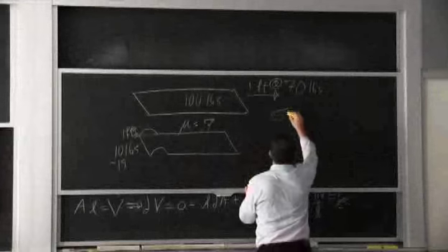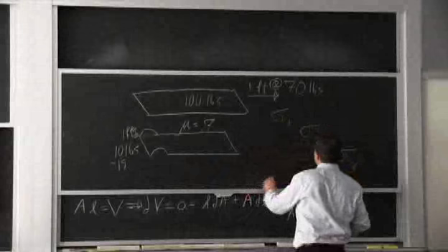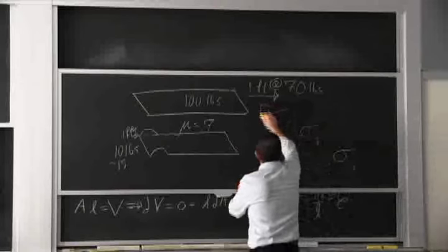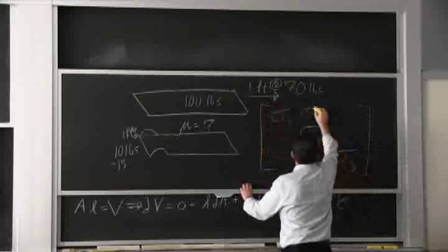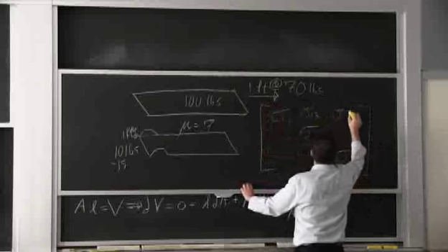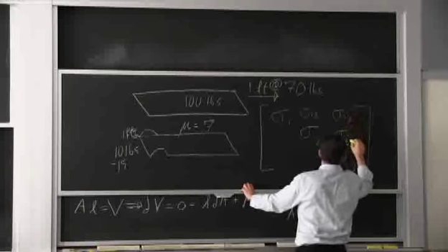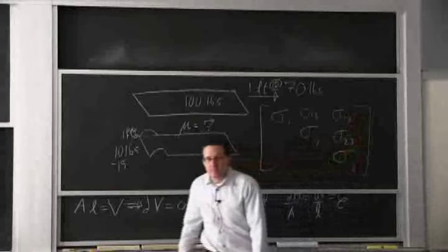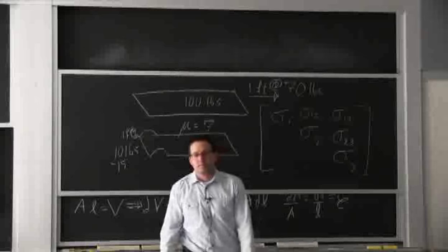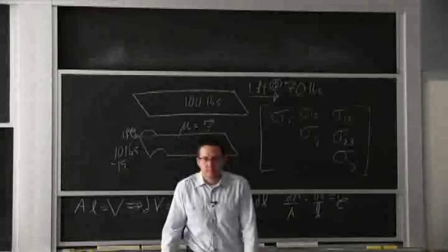components. The hydrostatic component is sigma 1 plus sigma 2 plus sigma 3, and that has no effect on shear or fracture. The other 6 components, this is actually what I was going to talk about briefly. First of all, there's actually only 3 of them that are independent. The other 3 that he didn't write down are equal to sigma 1, 2, sigma 1, 3, and sigma 2, 3. Those 3 are the shear components. The other 3 are the tensile components.